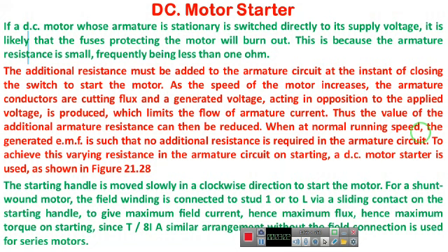V is the supply voltage, and the machine is just starting, so E is a little bit bigger than 0, or very small. So V over RA is very large. That means I is very high, so the starting current is very high, sometimes 3 or 4 times the normal current. So how do we decrease that current?